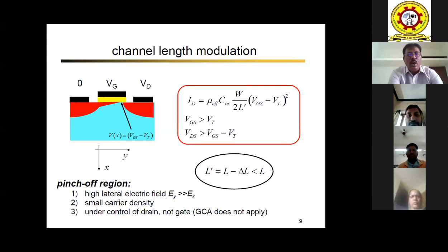Now what happens is, if this gate length is becoming less and less, like I said, now 5 nanometer is the current technology, right? So the gate length here is 5 nanometer. So the channel length is reduced. The minute the channel length is reduced, your gate voltage is also reduced because they are directly proportional. Thereby, your threshold voltage level is reduced and your VDD is also reduced. So these are all interconnected. So now, this is the normal practice.